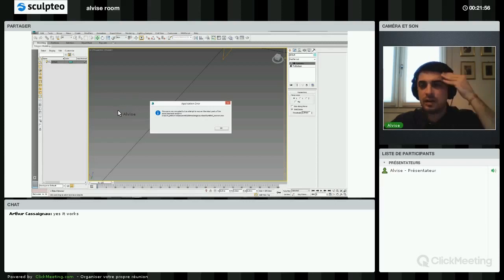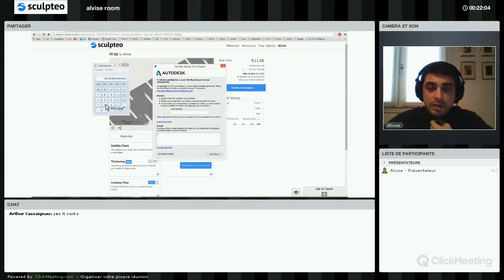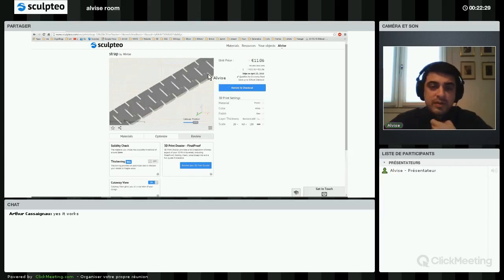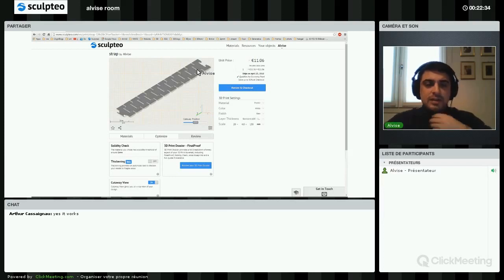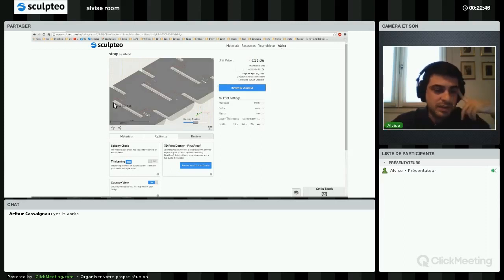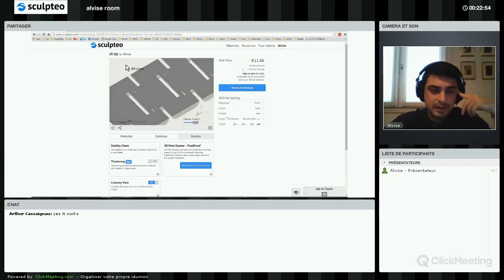So we have seen how to fix the clearance problem, and the last couple of things to do before the crash would have been just to apply the symmetry modifier to the body I was modifying, then copy it 12 times to reproduce the whole strap I was trying to fix. So I think we don't need to go back to reopen Max and conclude these couple of operations. They're very simple. And yeah, we covered, I think, the example dealing with clearance guidelines for interlocked parts. So we can proceed and go to the second topic, the second main design guideline. And as I introduced before,